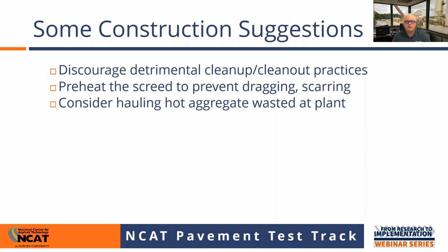And this is something that we're a big advocate of, because we struggle with these types of issues at the track. You got a lot of cold iron, and so we do everything that we can do to preheat trucks and preheat the shuttle buggy and preheat the paver just as much as we can. And I think that that's one of the reasons why we have performance. One of the contributing factors to performance problems at transverse joints is because we can have relatively cool mix that we're placing out there.